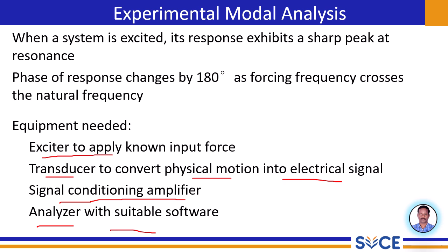The software then performs complex signal processing, often involving techniques like Fourier analysis to determine the frequency content of the signal, identifying the natural frequencies, calculating the damping ratios, and ultimately extracting the mode shapes or modal parameters.